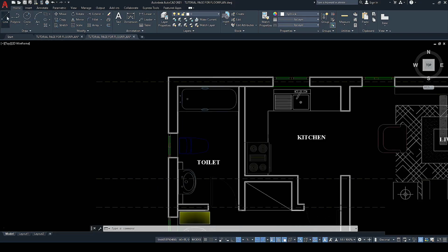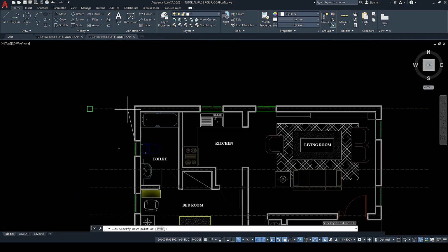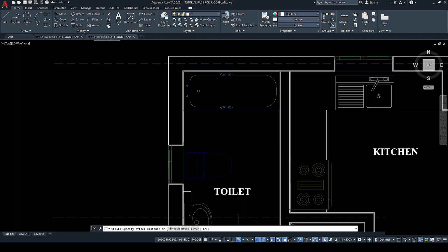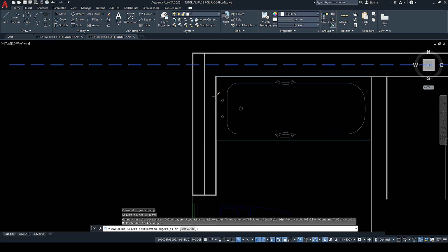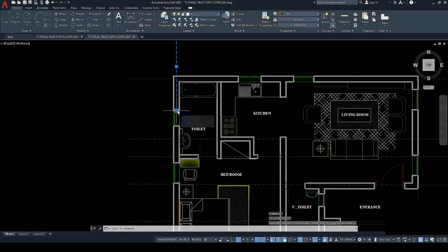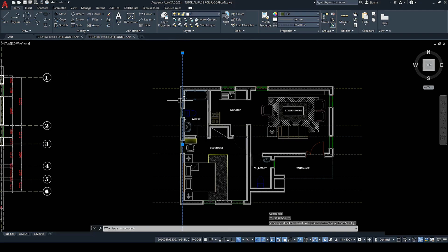So we'll do the same to our vertical grid. Just pick a line, same as we did initially. So we'll offset this 113 millimeters. We match the property of the grid to this. So we have this. We extend it outward and also in this direction.